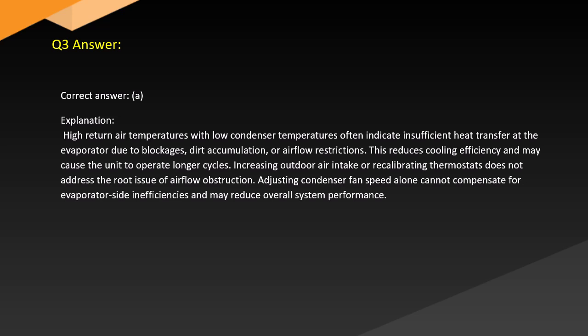Increasing outdoor air intake or recalibrating thermostats does not address the root issue of airflow obstruction. Adjusting condenser fan speed alone cannot compensate for evaporator side inefficiencies and may reduce overall system performance.